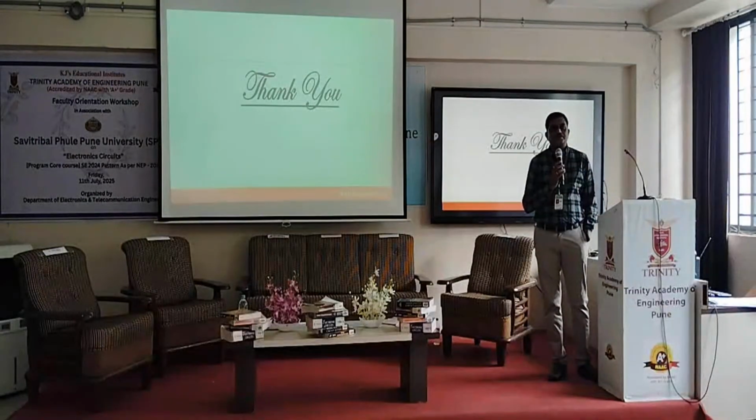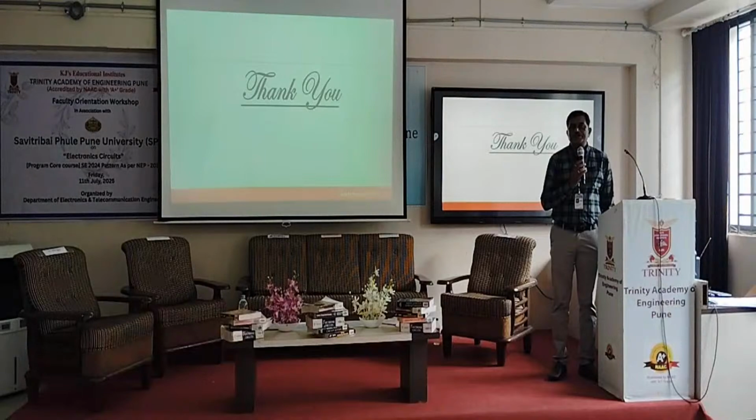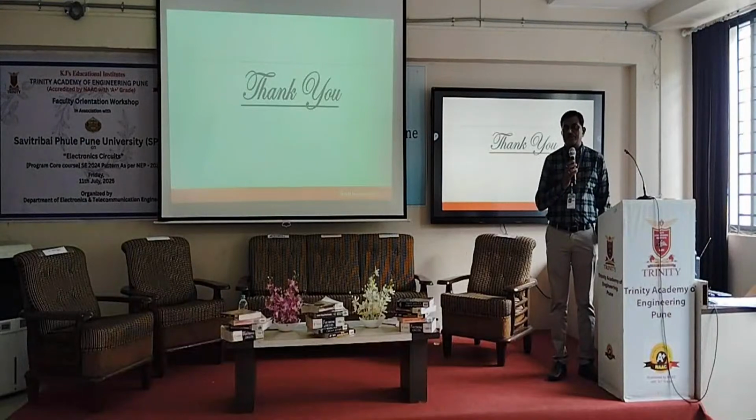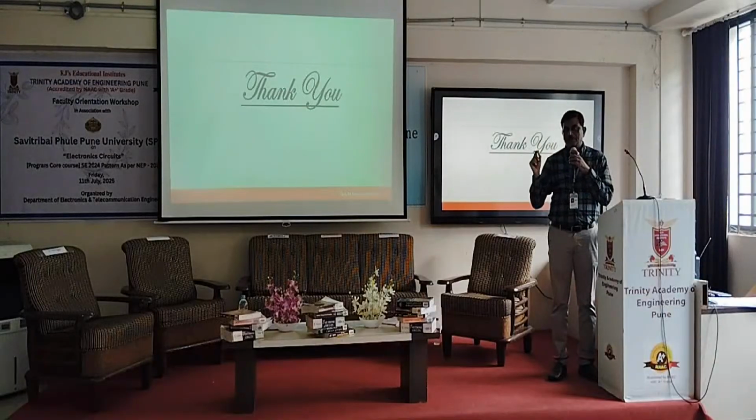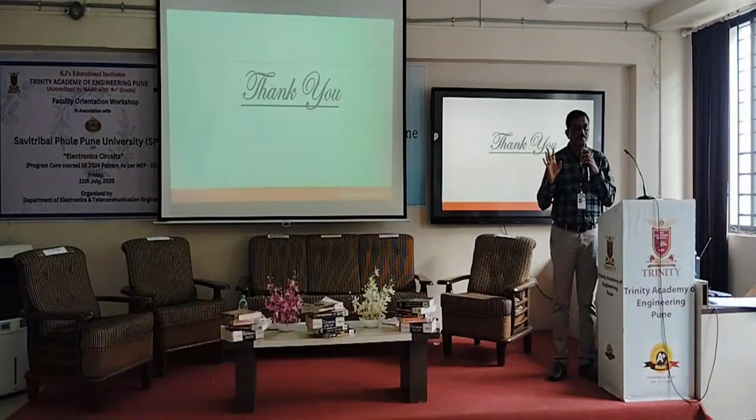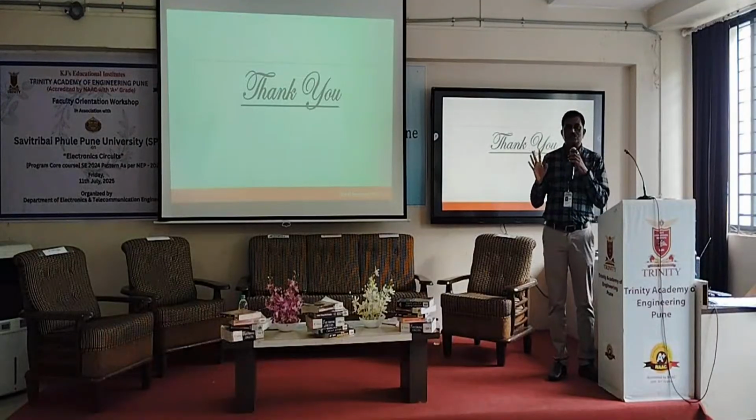These things I think are important. Yes, we only need to calculate R1 and R2 according to the VUT and VLT. So we are given the values of the VUT and VLT, calculate the values of R1 and R2, and design the circuit. It's okay.